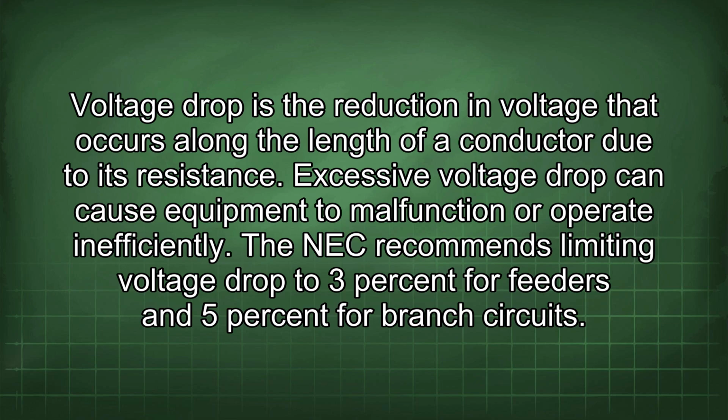Excessive voltage drop can cause equipment to malfunction or operate inefficiently. The NEC recommends limiting voltage drop to 3% for feeders and 5% for branch circuits.